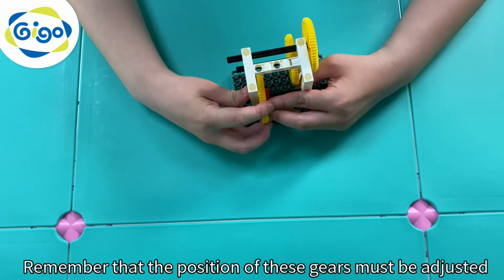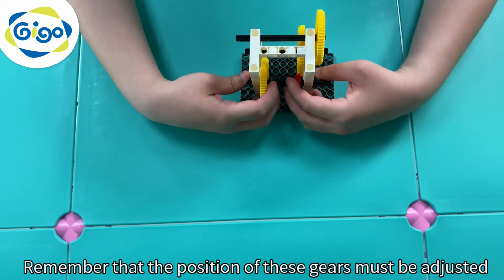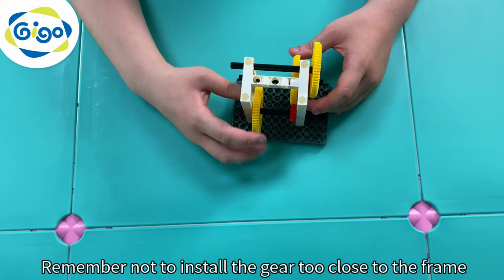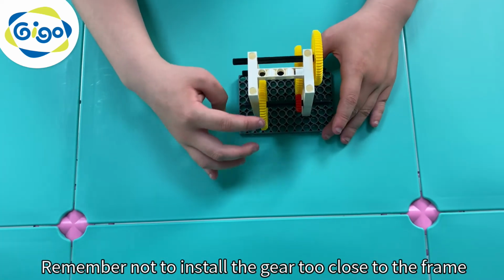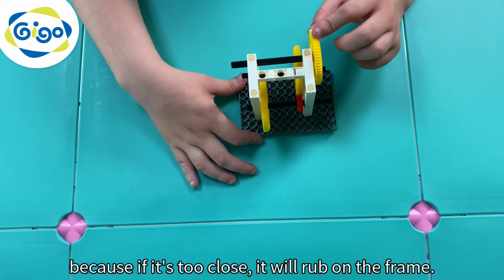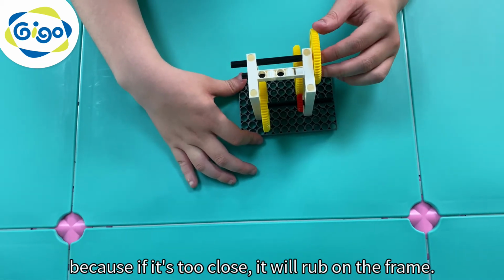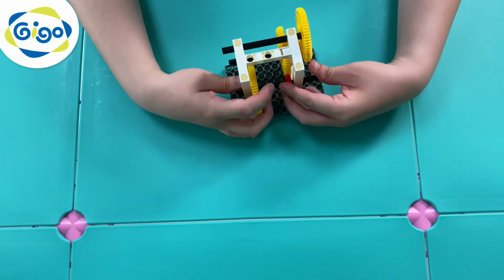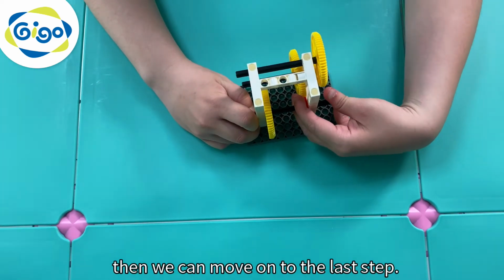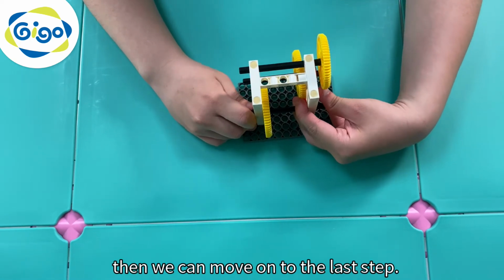Remember that the position of these gears must be adjusted to ensure that each gear meshes correctly. Remember not to install the gear too close to the frame when you're putting it on, because if it's too close, it will rub on the frame. After positioning the gear correctly, then we can move on to the last step.